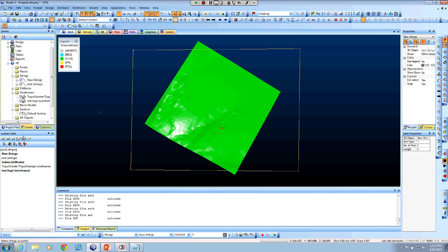And then what I'm going to do is create a fault surface. So I'm going to create a new, basically a new wireframe for the fault surface. So it's create new wireframe. So it's CNW, create new wireframe. And then I'm going to close that surface using ELI, end link, or it just basically fills in a closed string.